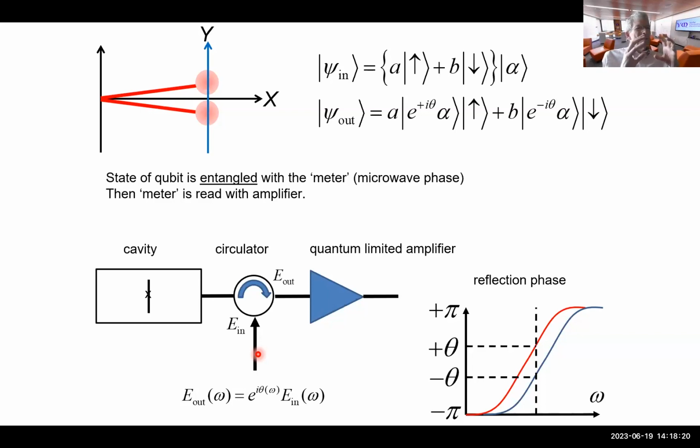Then for the purposes of doing quantum error correction or quantum computation or quantum simulations with bosons, with microwave photons, you want very high Q cavities because that's holding your logical information. And the purpose of the transmons is just to help you manipulate it and measure it. So a typical setup would have a high Q cavity, probably, at Yale, they tend to be 3D cavities, and also in Pittsburgh and other places. And then they may be coupled to a transmon, and then there might be a 2D coplanar waveguide resonator that's used for the readout.